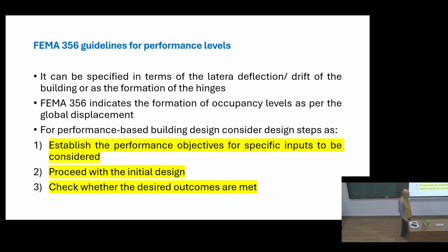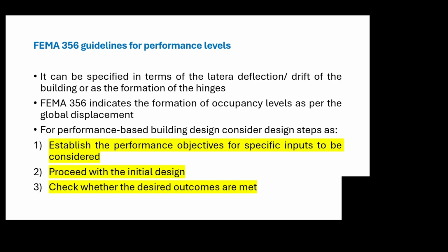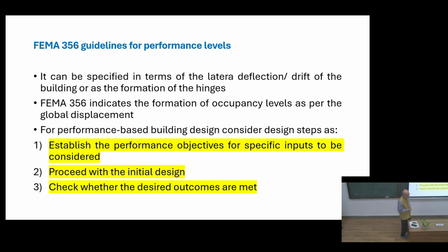Now, having said all those things, what FEMA says is that it can be specified in terms of lateral deflection. Now, we say performance, but what is meant by performance? In the elastic design which you do, at the highest load there is the highest deformation, and that is elastic. That means the deformation you consider is elastic. When you load and then remove the load, the structure should regain its position, and no deflection or deformation should be left once the load is zero. That is elastic.